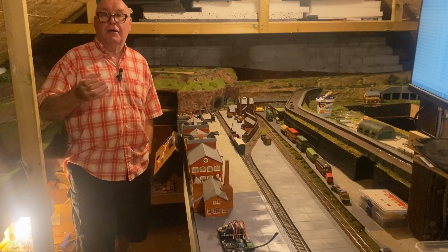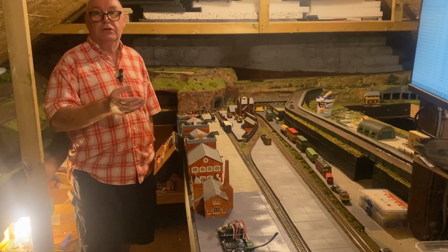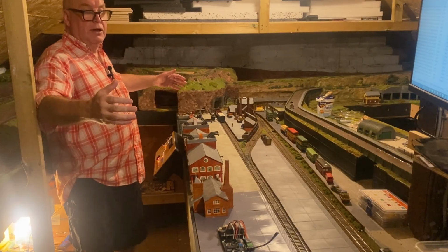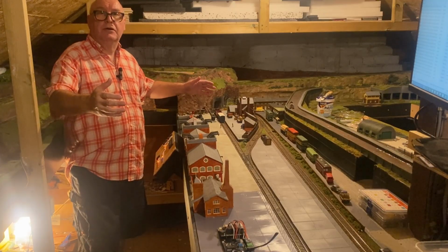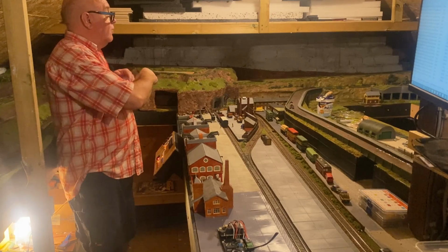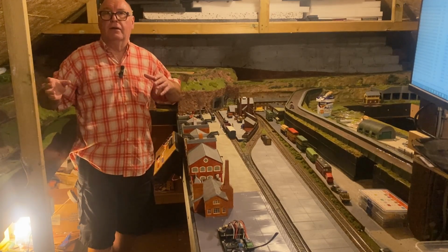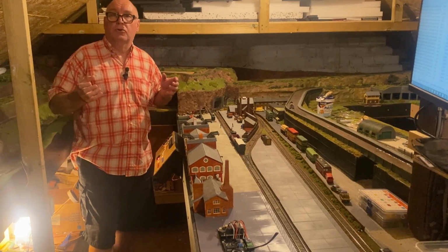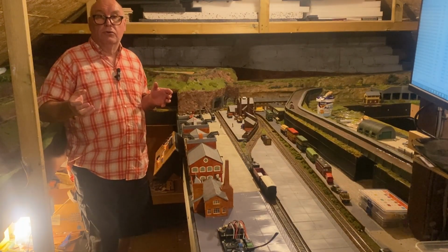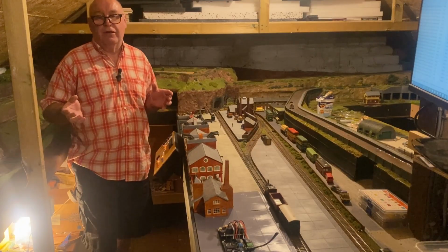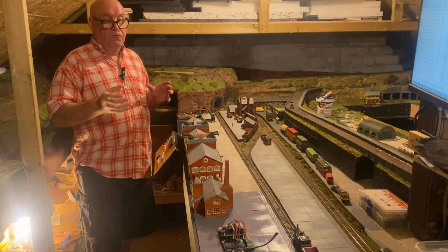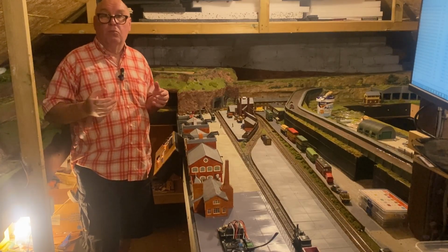So you might say to me, well, John, you could do all this with DCC-EX, and yes, you could. This section is only 8 foot by 4 foot, so an I2C bus interface for all this would work. But once you start spreading it out around the whole loft or slightly bigger, I2C can sometimes cause issues. Yes, we can extend it. Previously, this was all done using JMRI and the RS485 bus. Obviously, I've learned the new technique of using a CAN bus. Hopefully, this will now work the way I want it to.